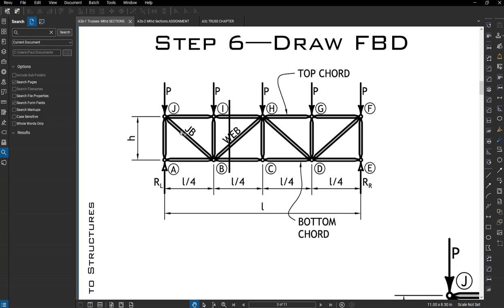So let's say I'm estimating the weight of this truss, it's early in a project, and the contractor's like, hey, I just want to know roughly how much this animal is going to cost. I could do a method of sections right through here, find the weight of those chords once I know the force in them. Then I could do a method of joints or a method of sections and get that member size. And then I can say, okay, all the webs are going to be based on this, and all the chords are going to be based on that. It's going to err a little bit on the heavy side, but that's okay. It gives people a quick way to start.